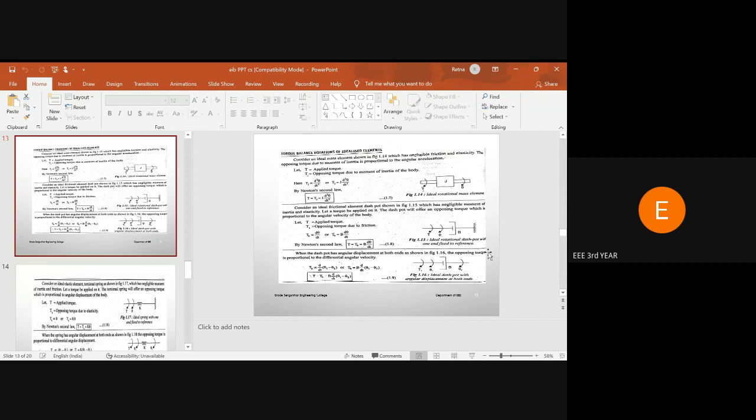Next, two ends open means applied torque due to dashpot Tb is directly proportional to d theta 1 minus theta 2 divided by dt. So, by Newton's second law, opposing torque due to dashpot with two ends open means Tb equals B into d theta 1 minus theta 2 divided by dt.